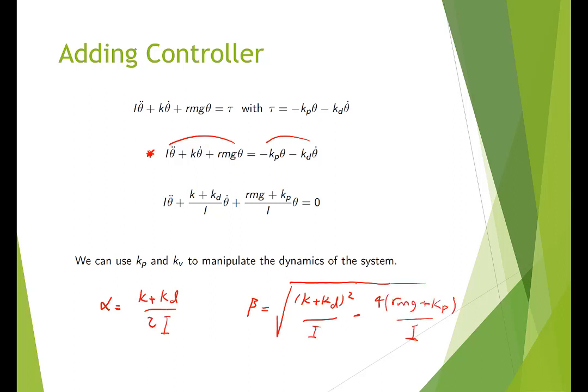So these would be the parameters for the equations after we add the spring and damper. You would see that now the constant for the damper and the constant for the spring show up in these terms. By looking at it, you can get an understanding of what that damper and spring do.